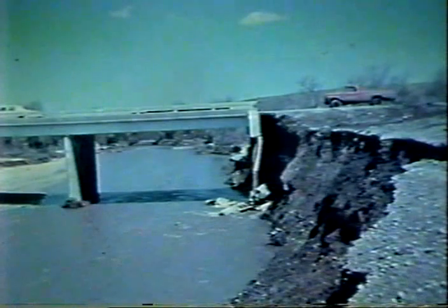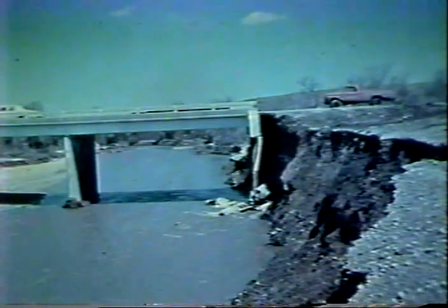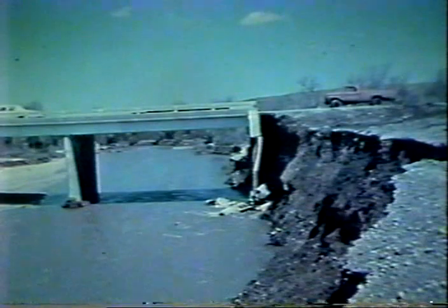A hydraulic problem is described according to its location, the physical process involved, and the effect on bridge use. In this example, the problem is at the bridge abutment, and the process is described as lateral erosion. The most common hazards are lateral erosion, general scour, and local scour. Other processes include channel degradation, accumulation of debris, and abrasion.